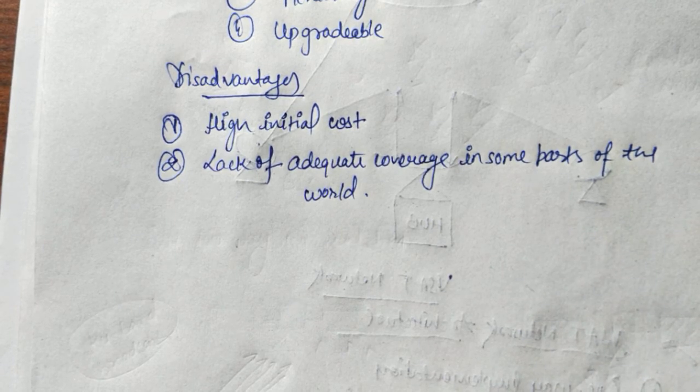The third is some service quality limitations, such as high signal delays. If we consider delay, it is quite high for this Vsat. Another disadvantage is the unavailability of direct links between various Vsats. Rain attenuation might also affect the performance of Vsat communication under rainy conditions.